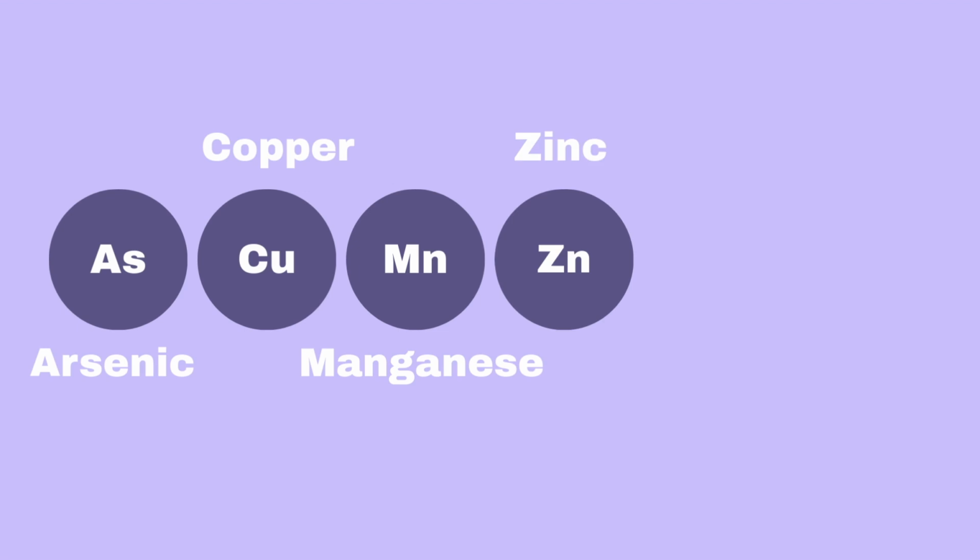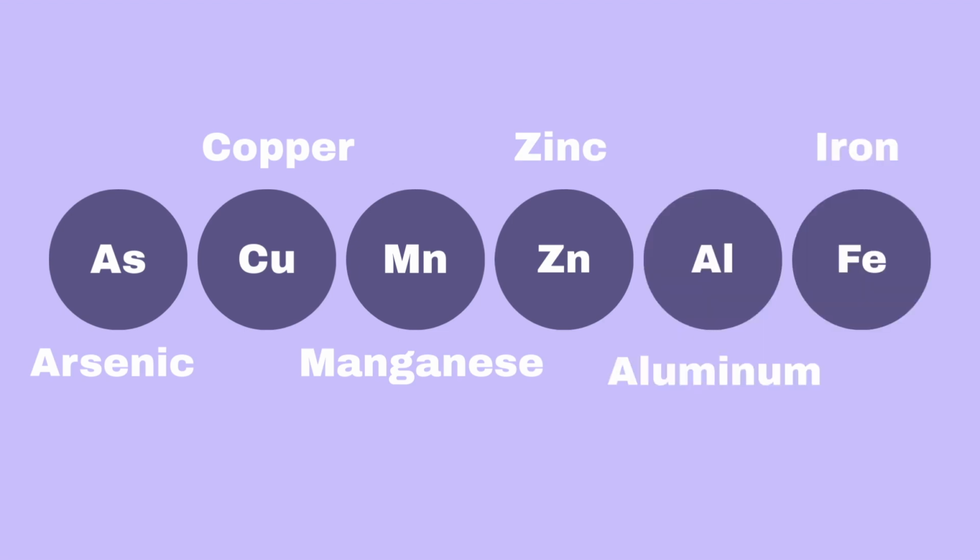Over the course of a year, our team was challenged with designing a passive water treatment system that used fungi to remove heavy metals from mining-influenced water. Our system was designed to be low maintenance and capable of handling a flow of 10 gallons per minute. It targets the removal of heavy metals commonly found in mining runoff, such as arsenic, copper, manganese, zinc, aluminum, and iron. In order to be successful, our system had to meet EPA discharge standards, run without electricity, and be practical for remote and rural locations.